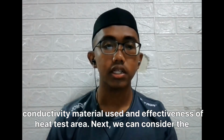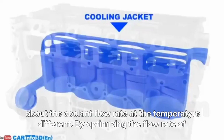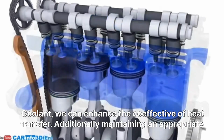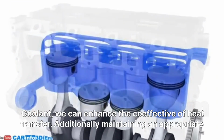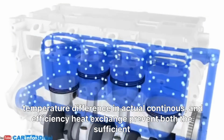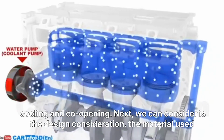Next, we can consider the coolant flow rate and temperature difference. By optimizing the flow rate of coolant, we can enhance the convective heat transfer. Additionally, maintaining an appropriate temperature difference will ensure a continuous and efficient heat exchange, preventing both insufficient cooling and overcooling.